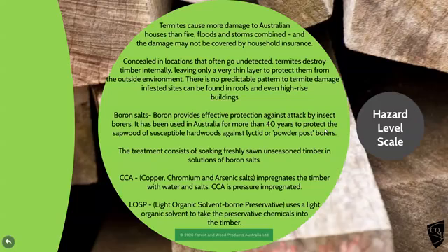If you hold up your little finger and look at its diameter, that's how wide the tunnel is that they bore. We've got borers in Europe too, and good treatments for them. Basically, the system is to soak freshly cut, unseasoned timber, so it's not been dried yet, in boron salts. You can also apply copper, chromium and arsenic salts, and there are light organic solvent preservatives as well. That all came from Forest and Wood Products.